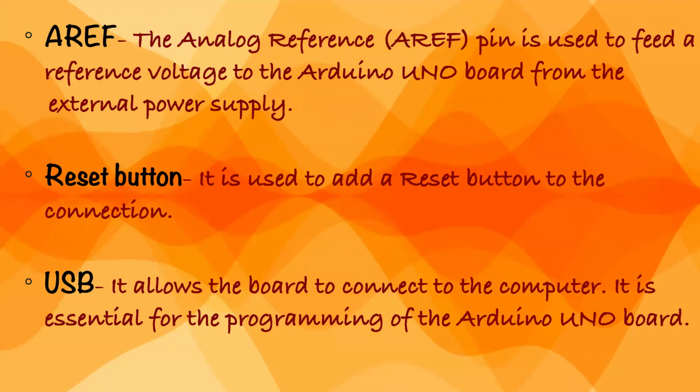Then comes AREF, or ARF, as we say it commonly. Okay, the analog reference pin. These things we have studied previously in the previous slides. That pin is used to feed a reference voltage to the Arduino Uno board from an external power supply. Whenever we want to supply reference voltage from an external power supply, we use the AREF pin. Clear?